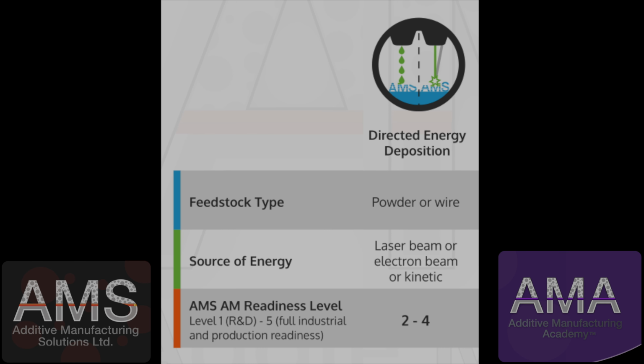In terms of readiness level, AMS perceives this technology as somewhere between 2 and 4. It's a very interesting range for us here. The kinetic or solid state DED process is normally known as cold spray. Though in the term cold spray you would assume the powder is cold, it actually gets quite hot. It is shot at supersonic speeds towards the substrate.